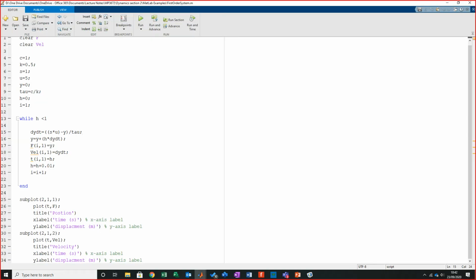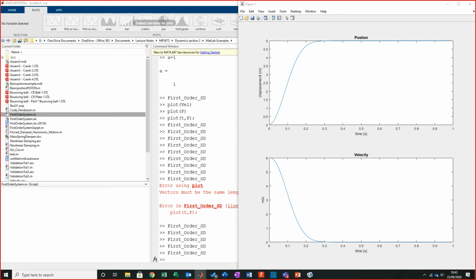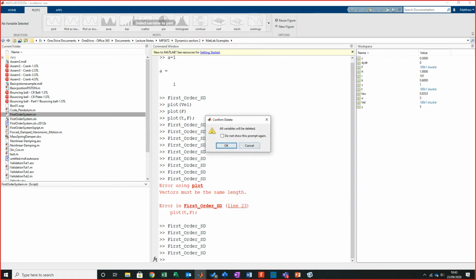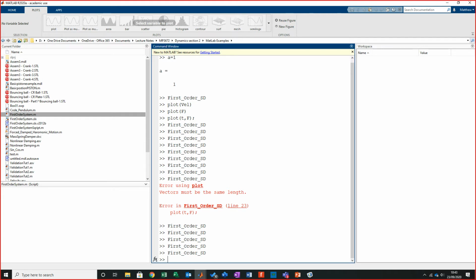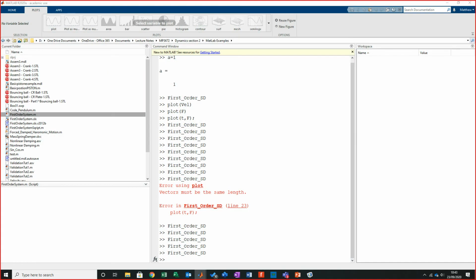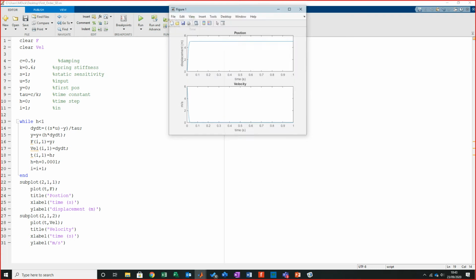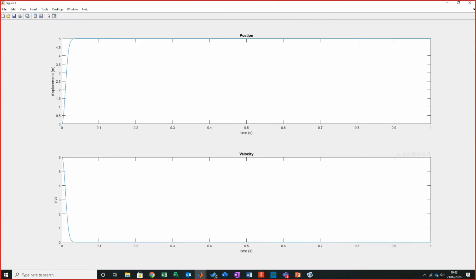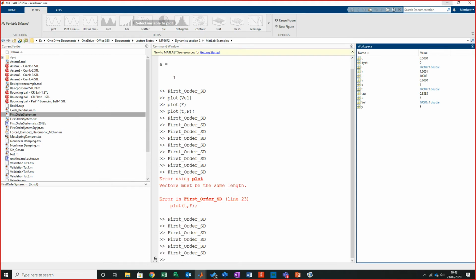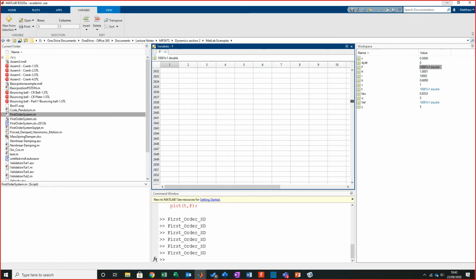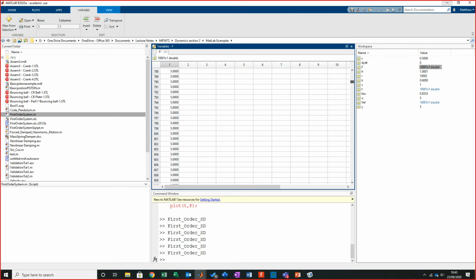Now what I would recommend is, when you're talking about iteration, if we make that step ridiculously tiny, clear all that. Two seconds. Where is it? There we go. Right, so if I go 0, 0 again, what you see now is we've got an initial response. But now what we're recording is mass amounts of data. So we've got 1,000 particular point outputs. Just by changing the value, I can make the iterations even smaller.